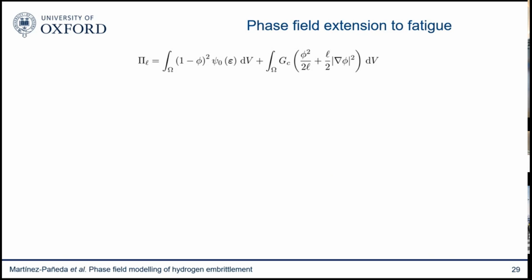But the good news is that fatigue builds on our understanding of fracture mechanics. Our engineering standards for fatigue build on Paris law or on fracture toughness, on ideas based on fracture mechanics. So this seems like the natural extension for phase field. So this is the question that I showed you before. Okay, what do we do when we have fatigue?